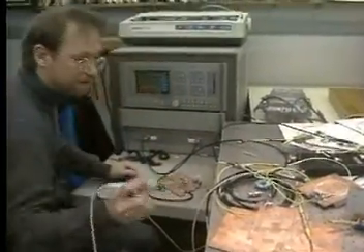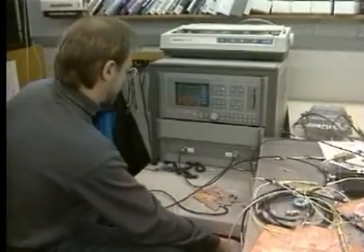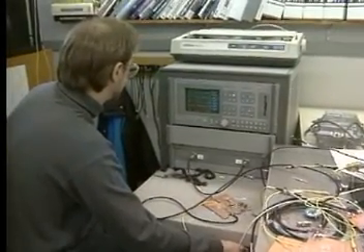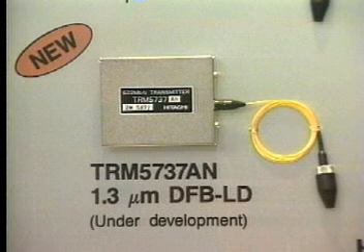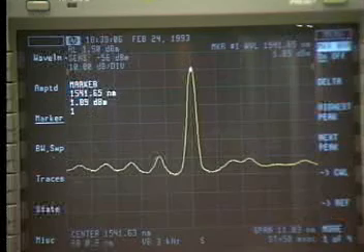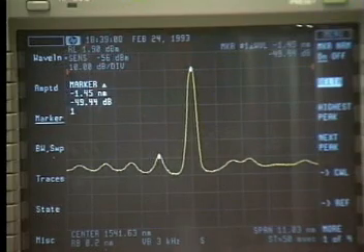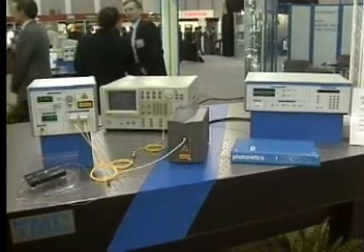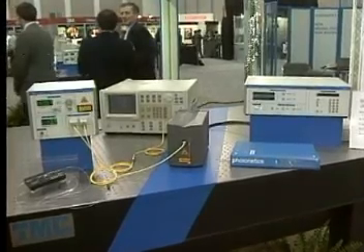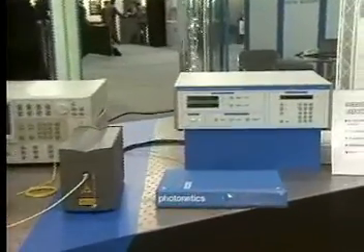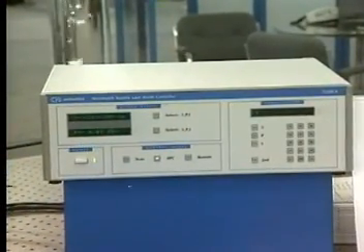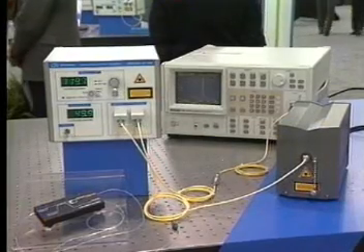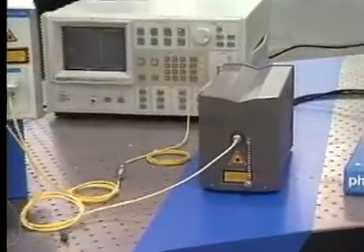For this reason, intense research and development has been devoted to constructing reliable lasers operating on a single wavelength. The distributed feedback, or DFB laser, uses an internal grating to allow only photons of one wavelength to reach the reflectors, thus suppressing the development of side modes. In some fiber systems, like those using wavelength division multiplexing, it is imperative that the optical sources used have a very narrow spectral width and stable center wavelengths. This is required to ensure that the receiving equipment can separate the optical carriers.